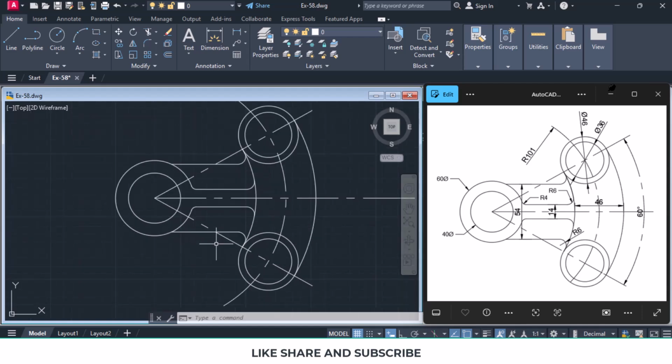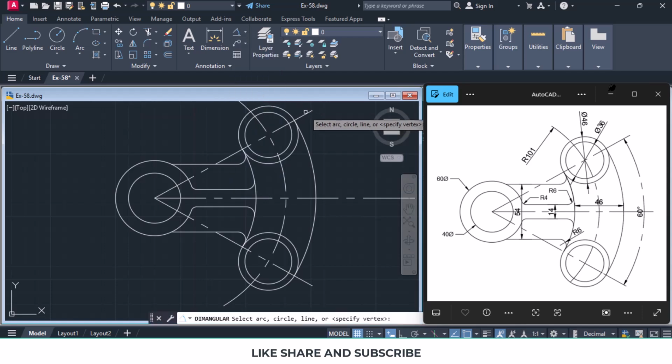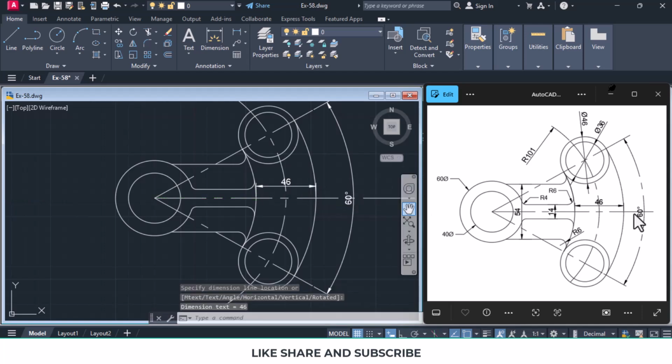Now we are left with only dimensioning. So we'll begin with this angular dimensioning. So we click over here and select angular, and click over here and over here, and we get the angle as 60 degrees. Then we want this linear dimensioning. So we'll select linear dimensioning, then we'll click here, and it is 46 units.